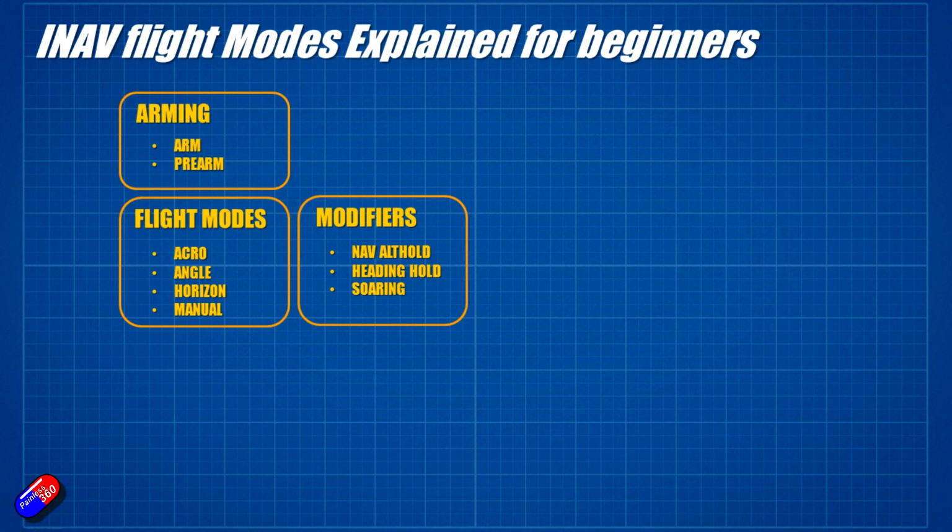And the last one is a mode for soaring. Now this is relatively new. Soaring is one of those cool things that allows you, if you are a glider pilot, to basically fly INAV, and INAV is still going to behave well, even though essentially you've got the motor turned off as you're gliding around. There are much more sophisticated glider setups, including things like automatic thermal soaring and hunting in things like Ardu plane. INAV isn't there yet, but if you want to put INAV into a soarer, this mode is there for you.